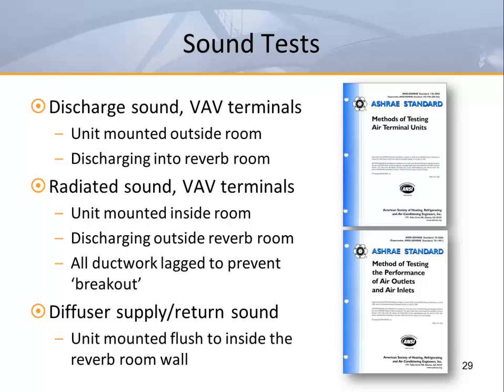Grills and diffusers are mounted on the end of a large pressurized plenum that ends inside the chamber. Products that are designed to be ducted must be fitted with a short stub duct and a bell mouth transition before mounting them on a plaque at the end of this plenum. This is done to create a non-turbulent neck condition to simulate a ducted connection. The same setup can be used for testing both supply and exhaust devices by simply reversing the direction of airflow.